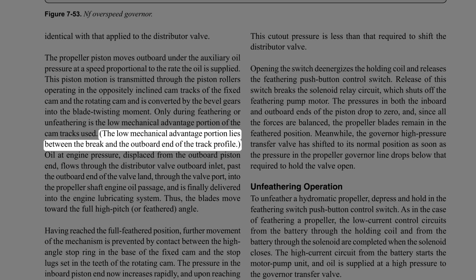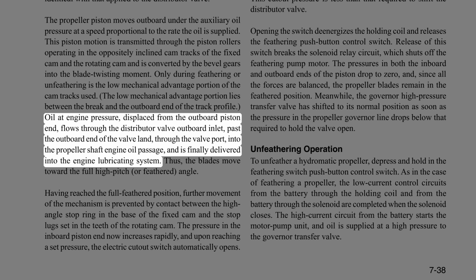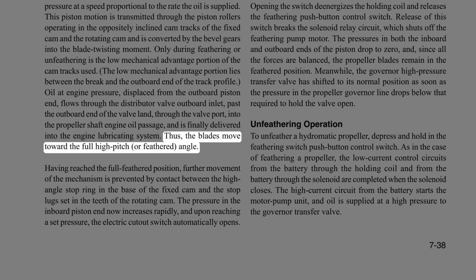The low mechanical advantage portion lies between the brake and the outboard end of the track profile. Oil at engine pressure, displaced from the outboard piston end, flows through the distributor valve outboard inlet, past the outboard end of the valve land, through the valve port, into the propeller shaft engine oil passage, and is finally delivered into the engine lubricating system. Thus, the blades move toward the full high pitch, or feathered, angle.